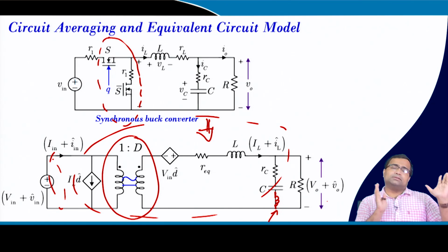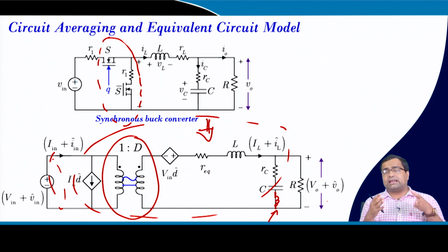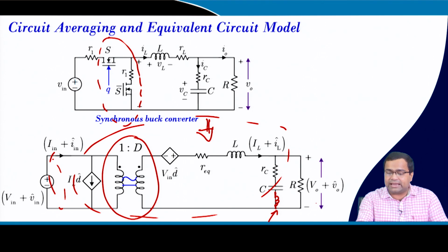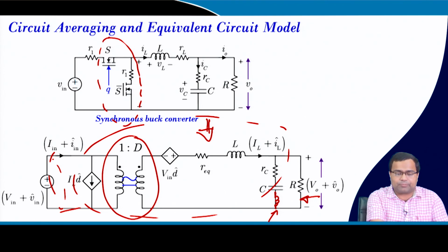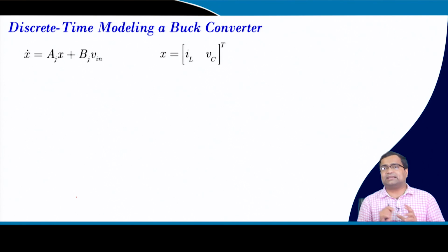So, that means the state space model can be obtained from mathematical equation, which is also fine, but this method can give more physical insight in terms of output impedance, in terms of input impedance, in terms of audio susceptibility, control to output transfer function. So, it will give more physical insight.